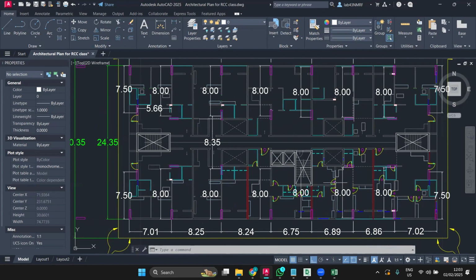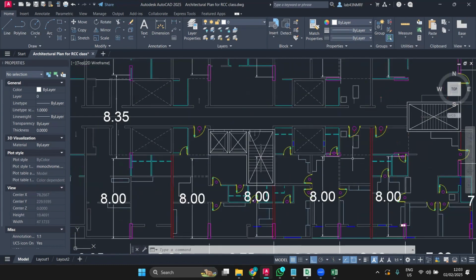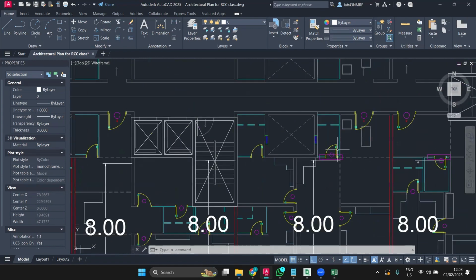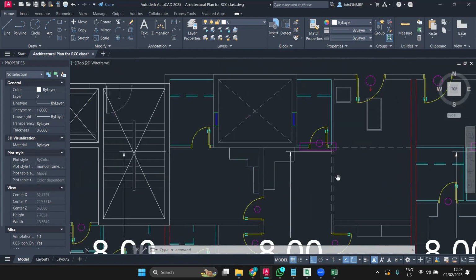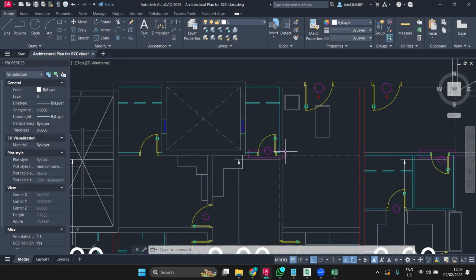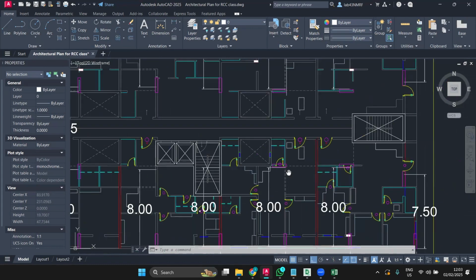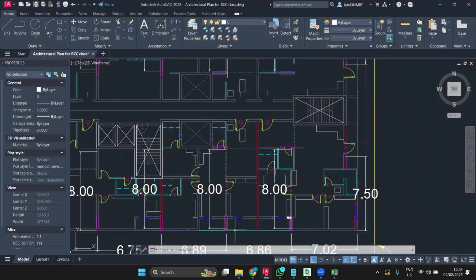You have to extract the reinforcement for the columns and beams, slab design, foundation design, and in terms of checking, the serviceability checks for deflection, displacement, and drift. If the drift fails, you also need to advise. If the displacement fails, you also need to tell me, because we all discussed those things in the class. If it fails under displacement, what do you have to do? If it fails under drift, what do you have to do?